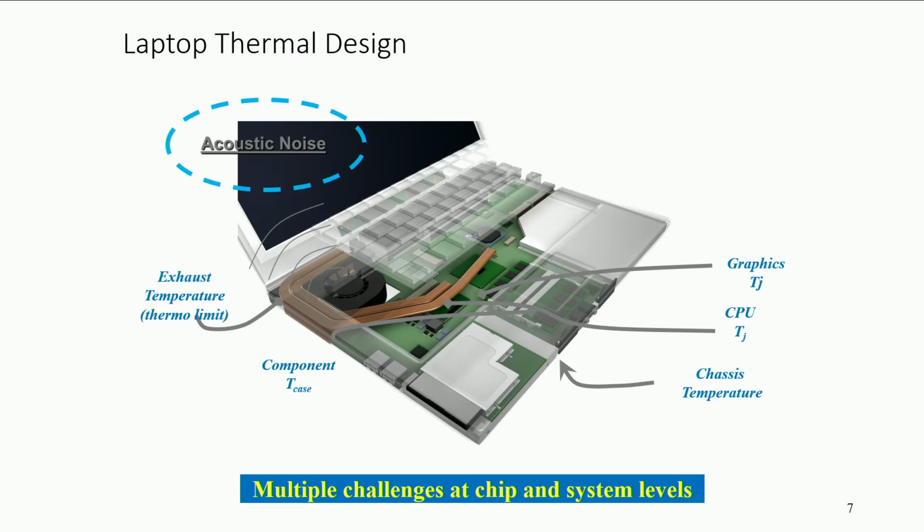Now, how are they getting cooled? I have just one fan. This fan typically in the laptop operates in an evacuative mode. There are pressurized modes as well, but most of them are evacuative modes. What does it mean? It means that the pressure inside the laptop is subambient. The fan is actually sucking in air. Through what? Through all the vents that you see on the bottom side, on the side, etc., except one which is this exhaust vent through which it forces it out.